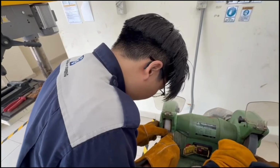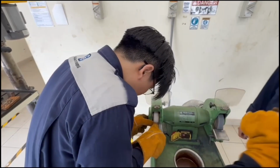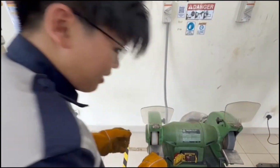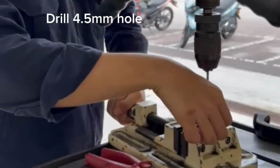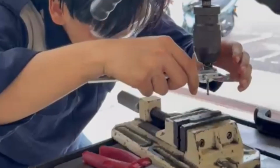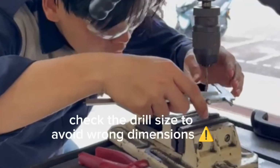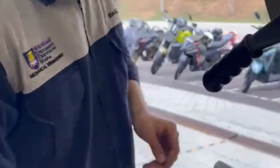Once the outline was marked, the workpiece was shaped into a half circle using the pedestal grinding machine. After completing the profiles, we drilled the hole using a 4.5 mm drill bit. Before the drilling, the drill position was checked to ensure the hole was aligned correctly and met the required dimension.